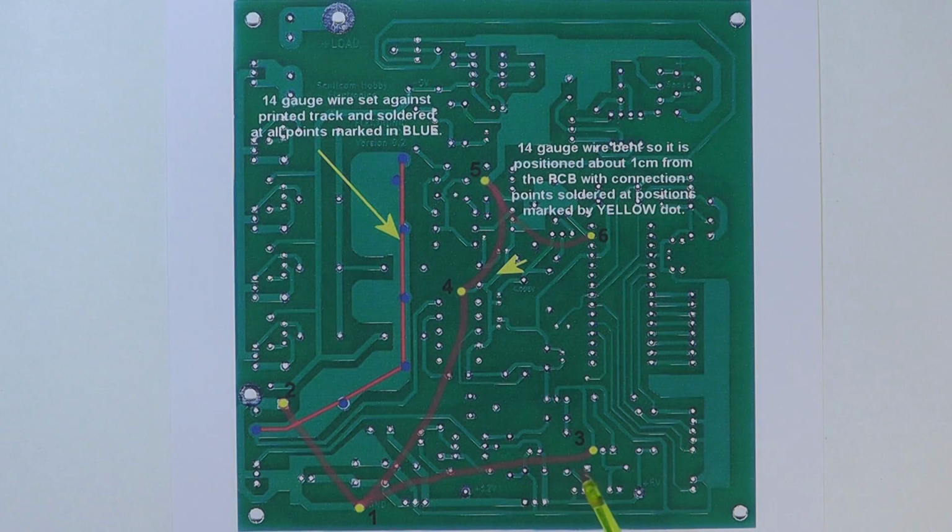Now I've actually put together a little information sheet just illustrating exactly where you connect the extra copper wire to on the underside of the PCB, and I'll make this available to you as a download, so it'll make it a little bit easier for you to add the wire, and it shows you clearly all the points where the copper is soldered onto the main PCB. You can also see here it shows you the extra copper we've added to the print around the source return resistors on the power MOSFETs. So this will be made available to you. Also on this information sheet there are some additional details of exactly where all the connections are made.